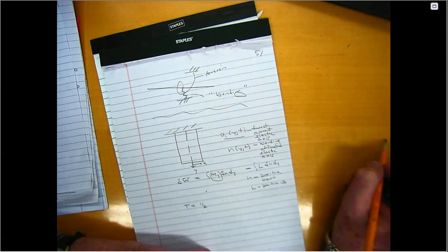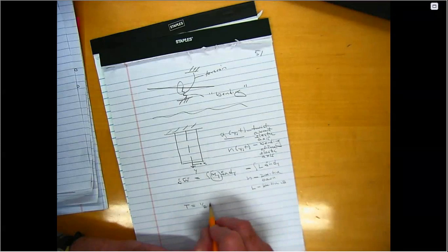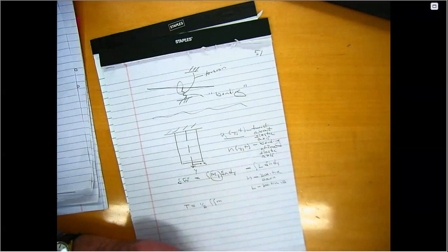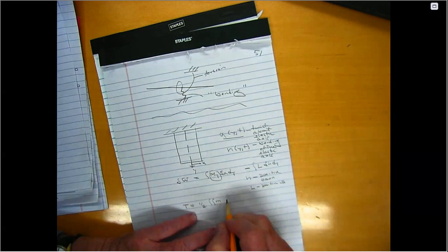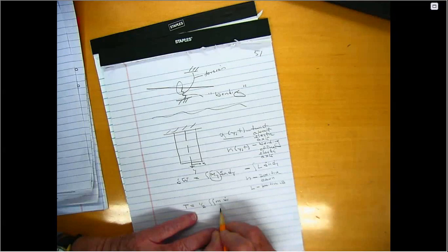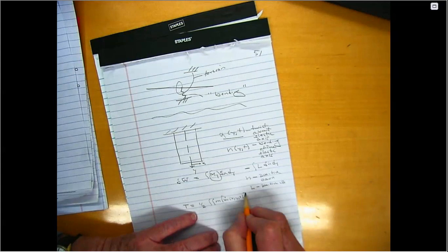Again, this is the sign convention that people use. So I'm going to write this now as the mass per unit area times w dot, where the dot denotes the time derivative, and w depends on x, y, and t, squared, dx dy.